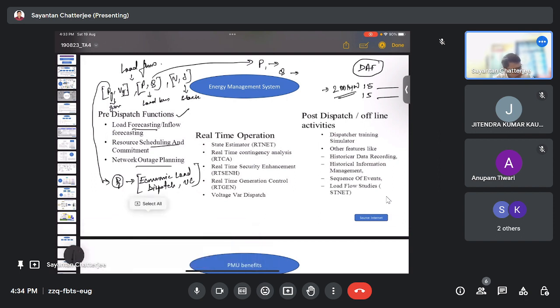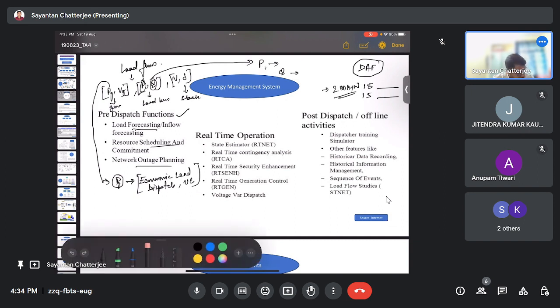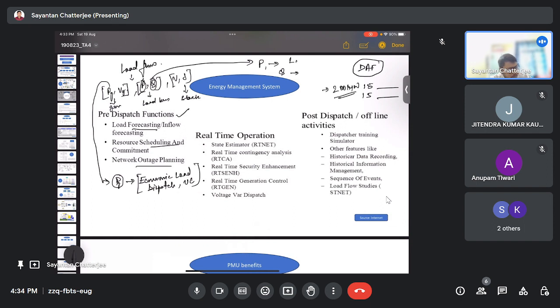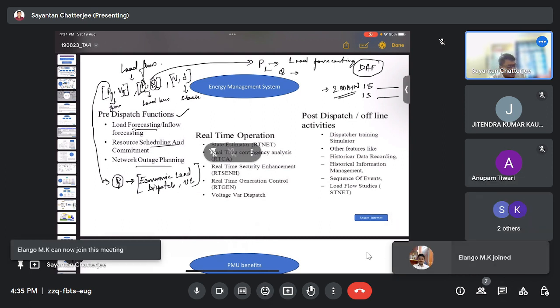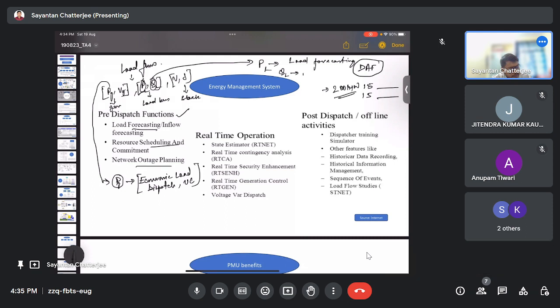Now coming to this P part and this Q part, the load P for the load bus is generally obtained using the load forecasting exercise. Based on the load forecasting exercise, this PG value, the P load value, is obtained. Let's consider PL, QL, and this QL is determined based on the active power loss minimization.